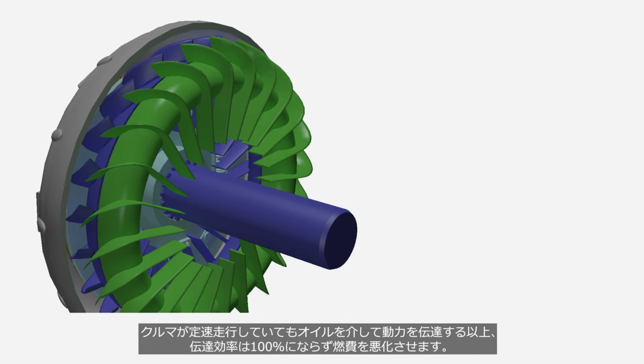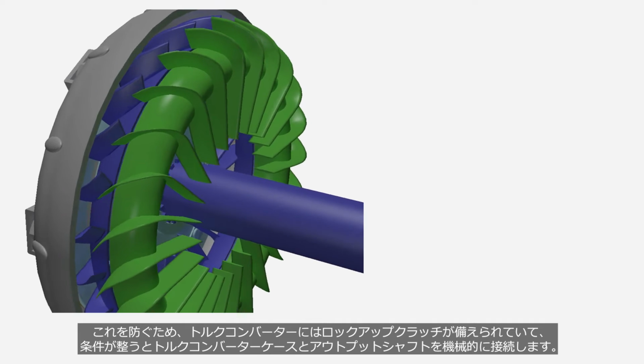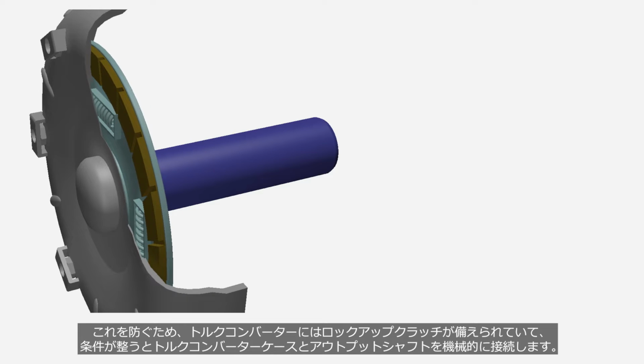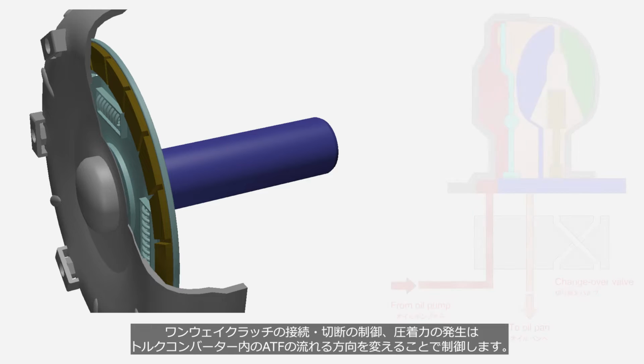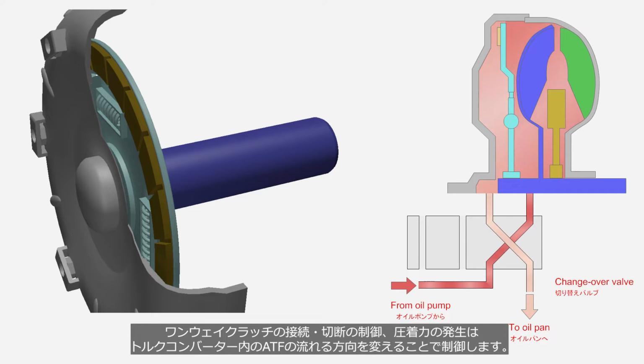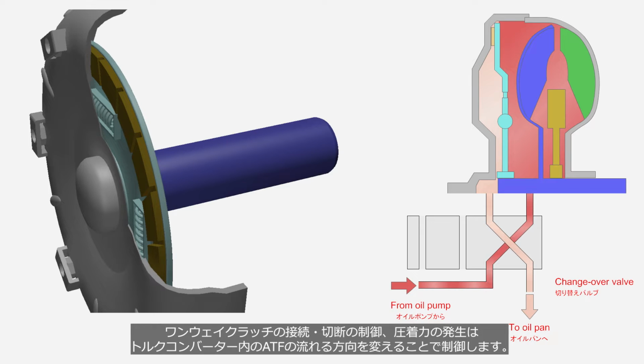Even when a car is cruising at a constant speed, because oil is used for power transmission, 100% efficiency can't be achieved, and it leads to decreased fuel efficiency. To prevent this, the torque converter is equipped with a lockup clutch. Under certain conditions, the lockup clutch mechanically connects the torque converter case and the output shaft. Control of the engagement and disengagement of a one-way clutch, and the generation of clamping force, are achieved by altering the direction of ATF flow in the torque converter.